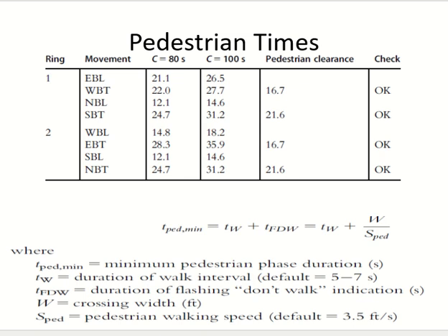If the left is separate, like here, where left has separate time and through has different time, you will check the time against the through movement. If they are happening together, then no problem. So we are only checking against the through movement. The required time is 16.7 seconds for crossing the north-south direction. He will either cross with the westbound movement or the eastbound movement.